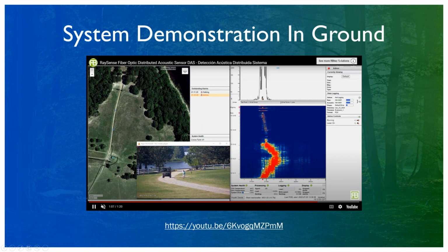And then it starts digging, and you can see that the digging has a completely different signal from a vehicle, walking, and digging. We get the digging classification, and after multiple digging, we'll get a digging alarm, and you will see that on the map, we placed it where he's digging. So about 10 meters, 30 feet from the vehicle. So with this system, although we have up to 50 kilometers of cable or 30 miles of cable, we can place the intrusion within 3 meters on the fence and roughly 5 to 10 meters in the ground where the intrusion is coming from.